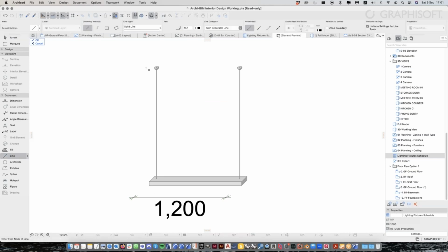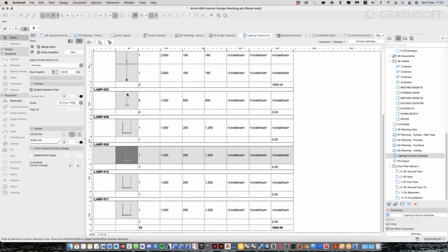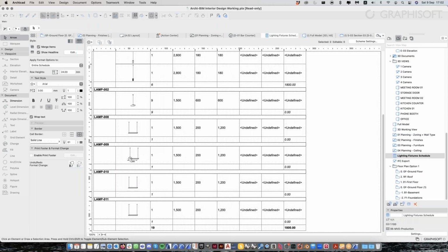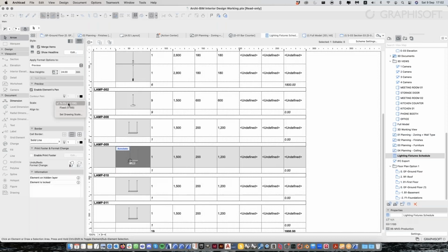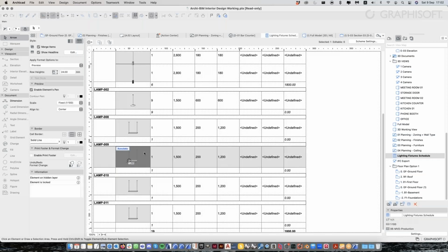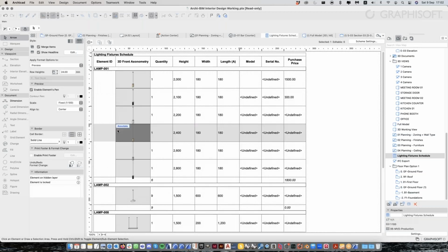And you can draw lines, I think, if you want. Okay, highlight, and just click OK. And here you go. You see your tiny little annotation. You can adjust the columns, of course, if you need to make it bigger. And you can even fix different scales of these things. So yes, you can annotate in your schedules, no issue. Although you may need to annotate one by one. Unfortunately, it's not that smart.